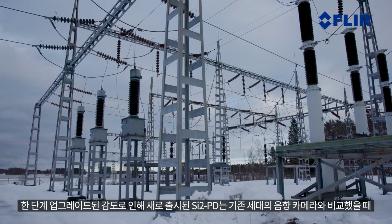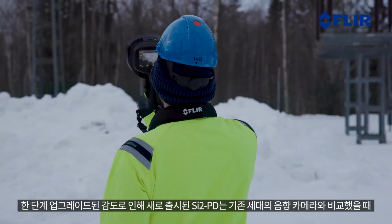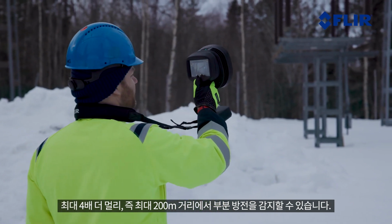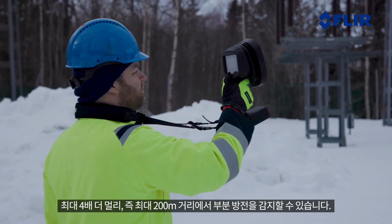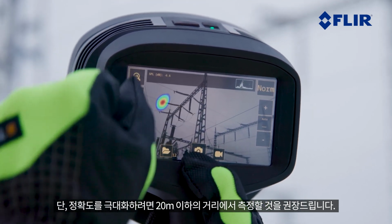With its improved sensitivity, the new Si2 PD is able to detect partial discharges from up to 4 times further away than with previous generation acoustic imagers, with distances reaching up to 200 meters. For the most accurate results, we recommend a distance of 20 meters or less.